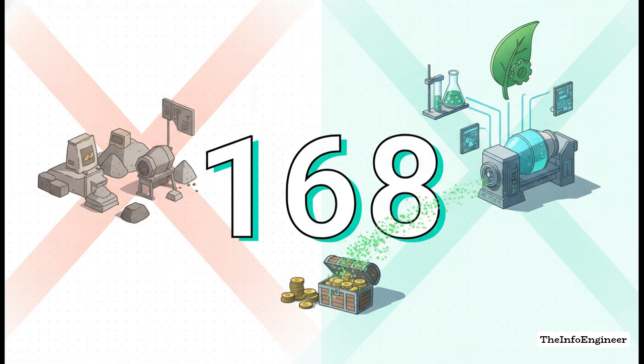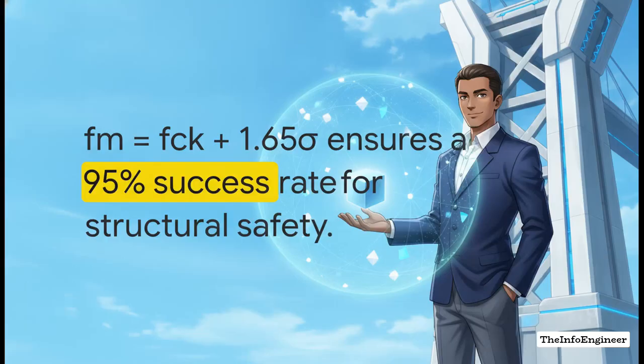So yeah, while a design mix absolutely requires an upfront investment in lab testing, the material economy on a large project is astronomical. You're saving massive amounts of money on cement, and you're significantly slashing the embodied carbon of the entire project. It's a huge win-win. And the best part? You achieve those massive savings without sacrificing even an ounce of safety. In fact, safety is literally mathematically engineered into the design mix through the formula for target mean strength.